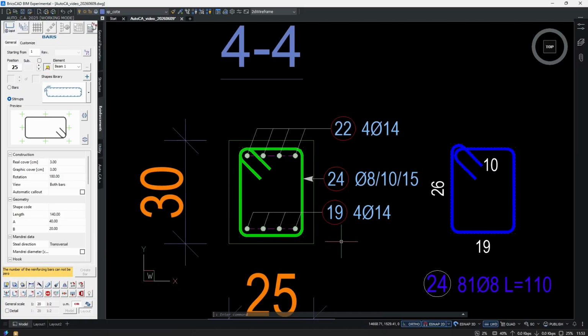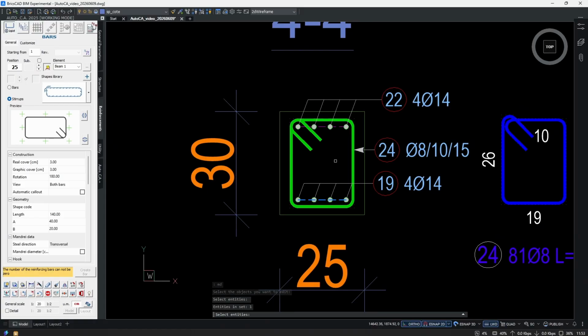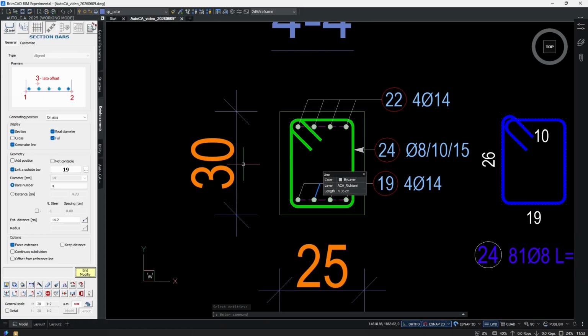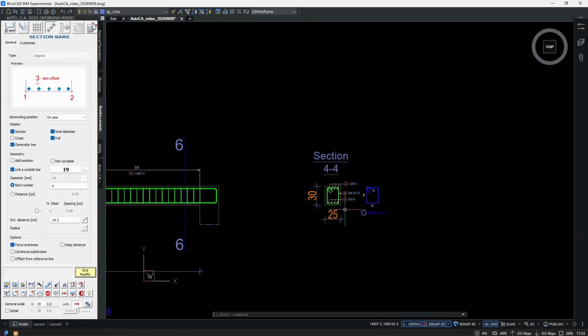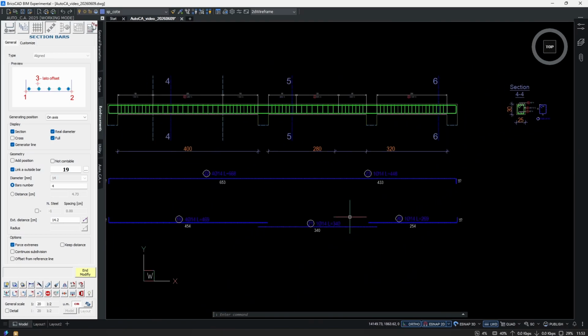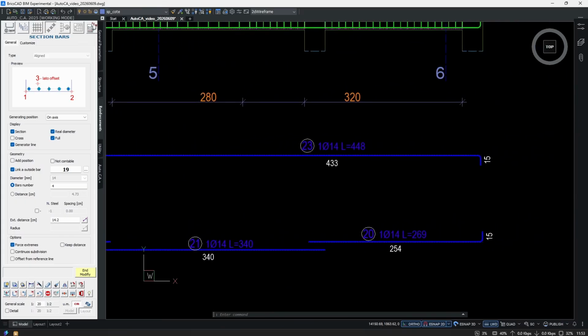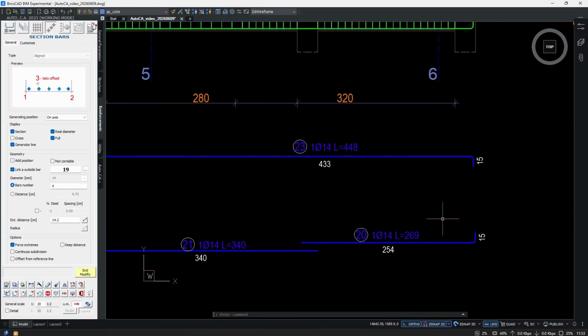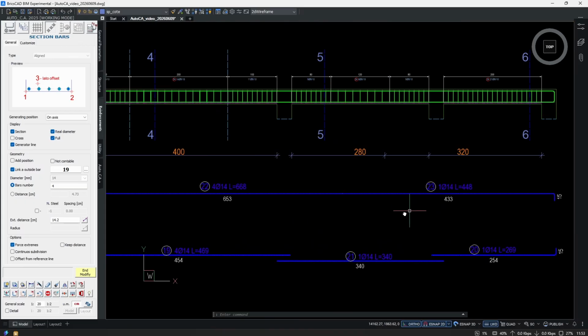And what I want to show you is that you can assign the same bar section distribution to multiple outside bars. So if you don't want to create physically 3 different cross sections, but still you want to distribute all these bars to avoid inputting the quantity manually, then you can do this.